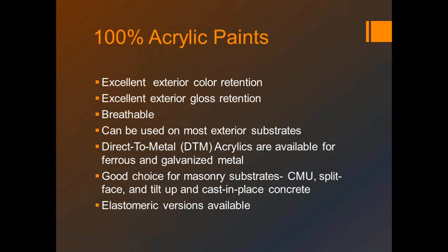I guess I'm relying a little bit on what we talked about last month, because vinyl acrylic is another kind of latex paint, but it's a vinyl resin and an acrylic resin blended together. There are and have been some of those that are exterior products. Mostly vinyl acrylics are used interiorly. They do a great job interior. They're not as UV, ultraviolet light, resistant as 100% acrylic is. But you can get flatter flats with a vinyl acrylic, and it has some really good benefits for interior usage. But whenever we're talking about exterior, the 100% acrylic paints will really do a better job for you in an exterior environment.